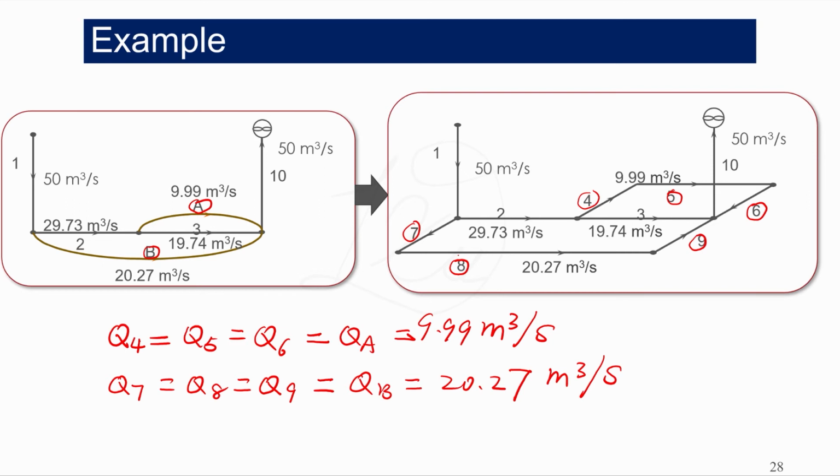For example, if I ask what's the pressure drop in airway 8, P8 equals R8 times Q8 squared. R8 is given and Q8 is calculated here. By using the calculated numbers, we can calculate the pressure drop in airway 8.